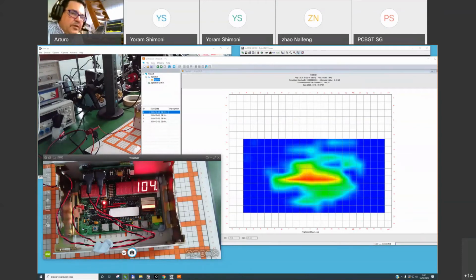The activity of this first harmonic, or the third or the fifth, is in the PCB, and the PCB is on top of the slots. It is in the same position, so the coupling is the same. The 125, 130 megahertz activity is going through the cables, and separating the cables reduces the coupling at that VHF frequency, but we don't obtain any change at 11 megahertz, which is coming from the PCB. Remember, with this technique you can evaluate different designs of your enclosures, the size of your slots and apertures. You can evaluate gaskets.